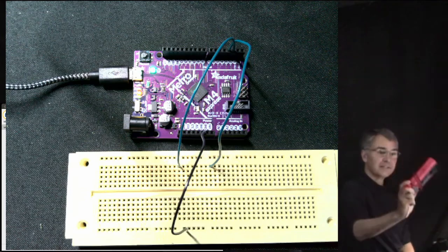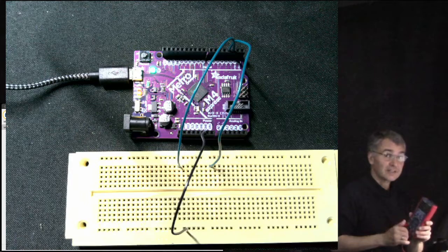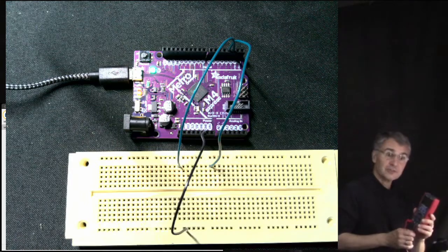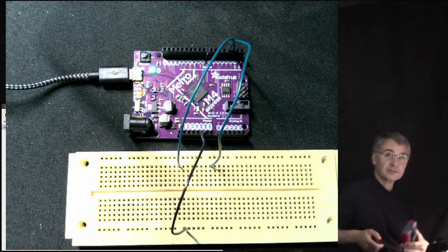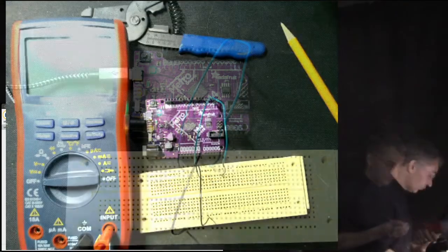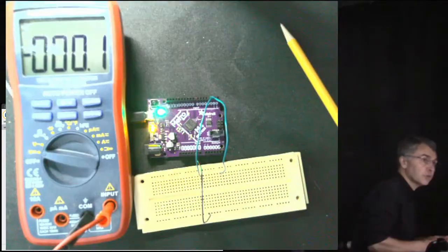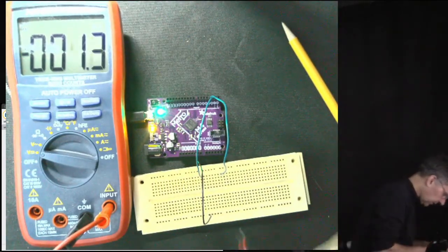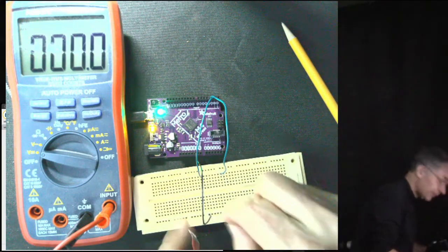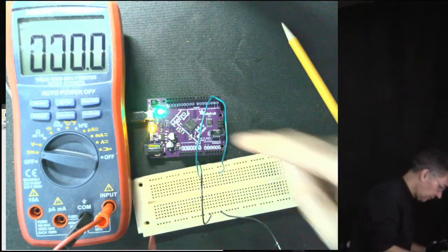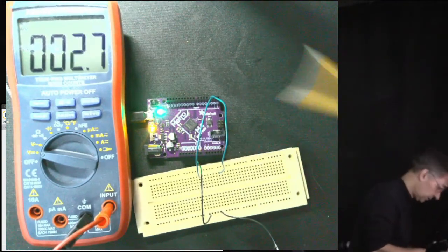I have here a handy device called a digital multimeter that can measure voltage, aka electric potential. It can measure current. It can measure continuity to see whether things are connected to each other. It can measure electrical resistance in ohms. So I will put this on DC volts mode. So I will show you that when I put the black wire of the digital multimeter to, well, I can put it down here on my breadboard's ground, but it's the same thing as putting it to ground over here since I have a wire between them.